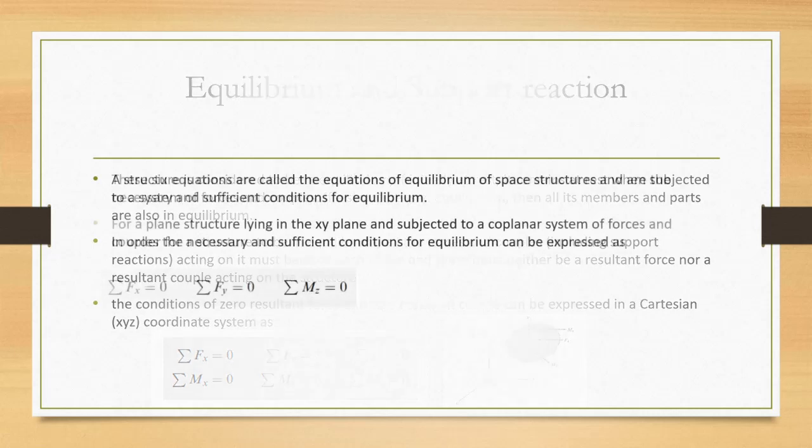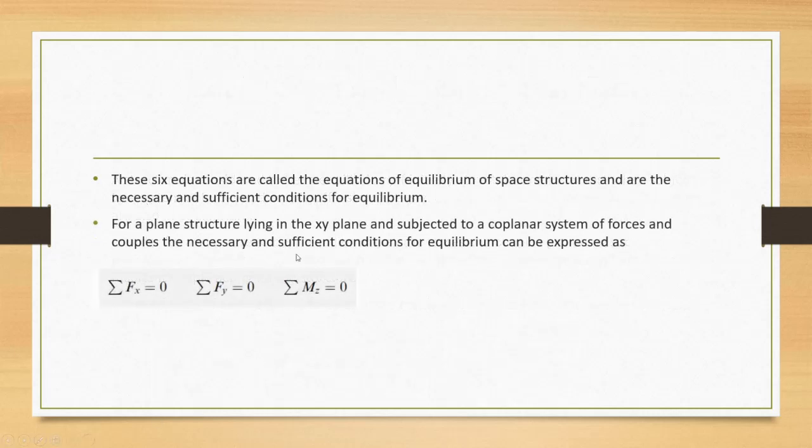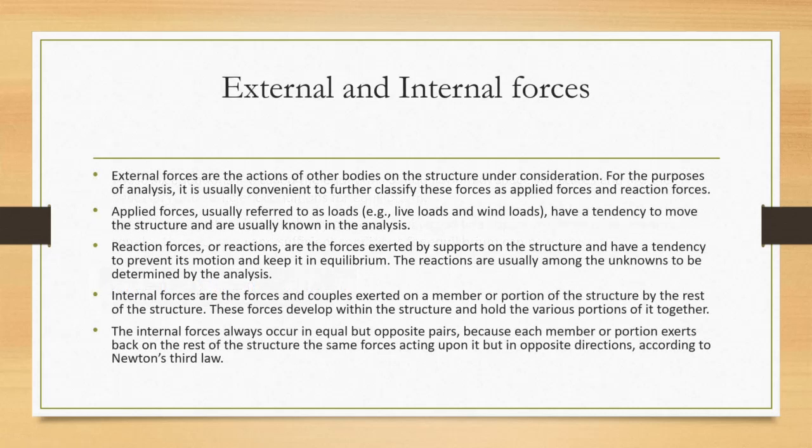So we'll be working mainly on 2D. That's summation of forces in the x direction, summation of forces in the y direction, summation of moments in the z direction. External forces and internal forces. Basically, external forces are loads that act on a beam, and these loads cause reactions, while internal forces are forces that keep the body, that is the beam, together.